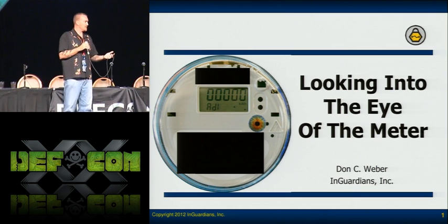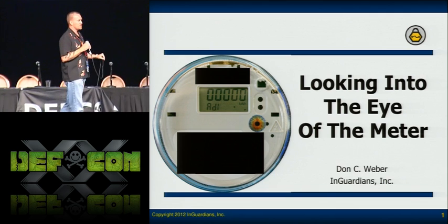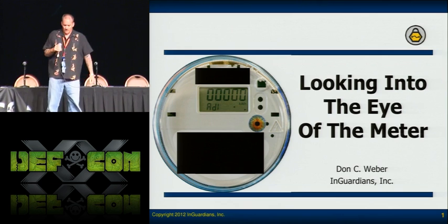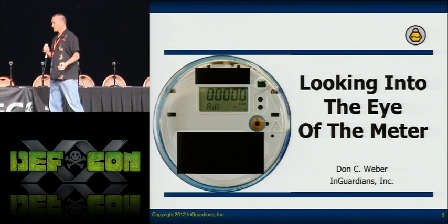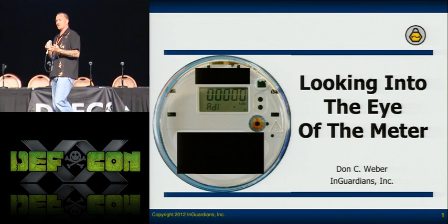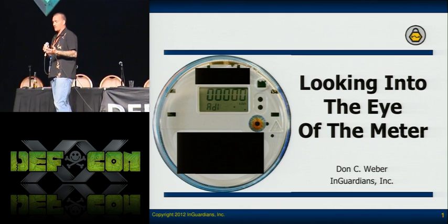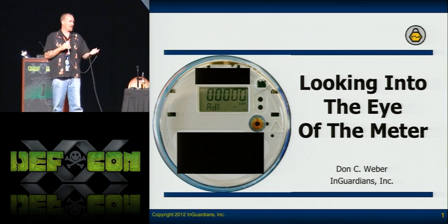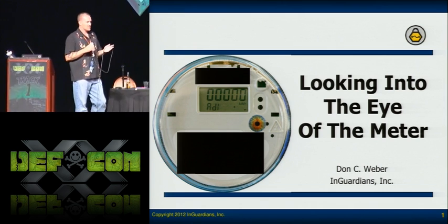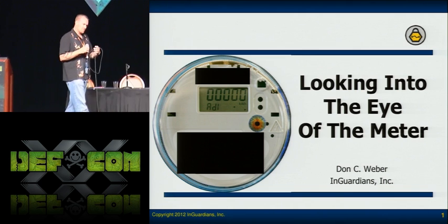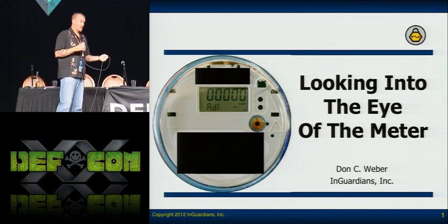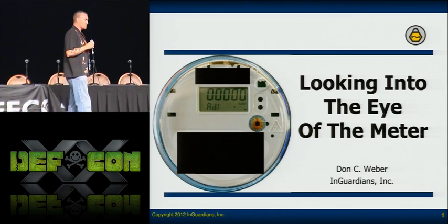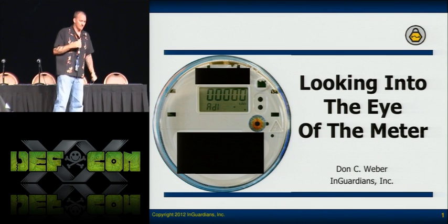But as soon as I picked it up, the first thing I noticed were 2 IR LEDs on the front of it, on the face of it. I'm like, what are these? And he said, well, when the field technicians have to make a modification to the meter, first they try to contact it with the radio because they all have radios in them. Okay? But if they can't contact it and it's some type of condition that they don't want to pull the meter off, lots of rain, really hot and they're really sweaty, blizzard conditions, they'll use the optical port to either pull data off or reconfigure it.